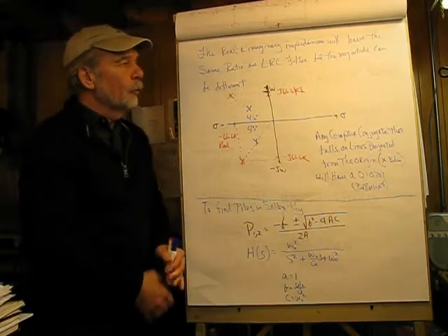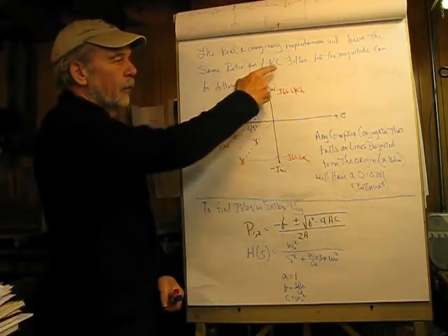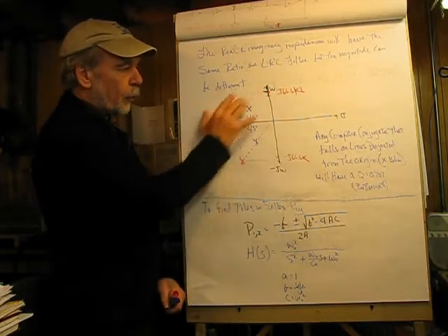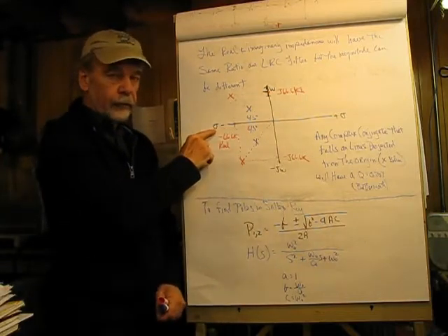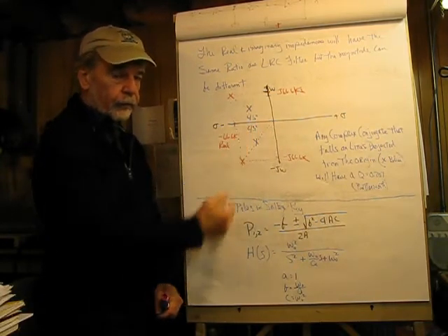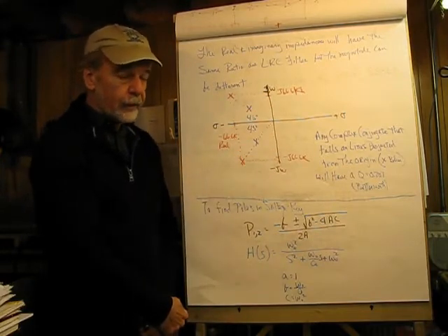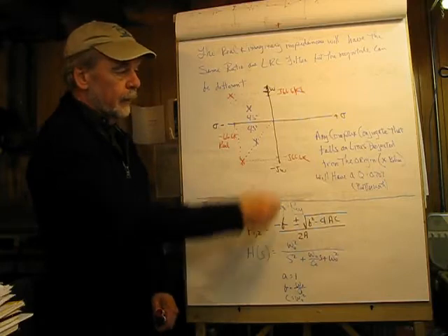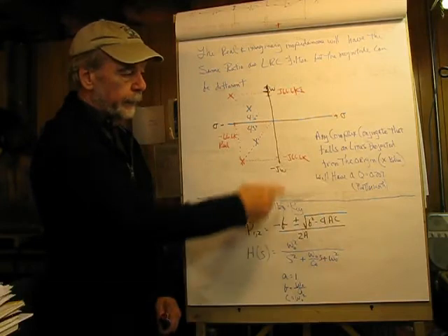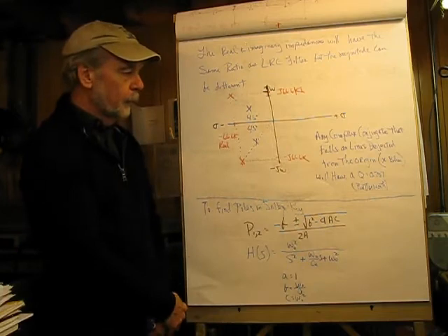So if we take a look at the real and imaginary impedances, we notice that they have the same ratio as the LRC. The magnitude can be different, and what we can see here is a pole zero plot. Here I have negative sigma, positive sigma, and we always have to be in the right hand plane if we're dealing with filters. Locating a pole on the J omega axis leads to instability, severe instability. And if we're over here, we either have an oscillatory issue in quadrant 1 or a growing exponential issue in quadrant 4, undesirable for our purposes.